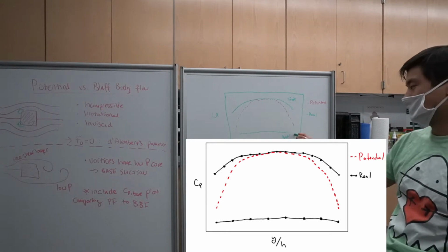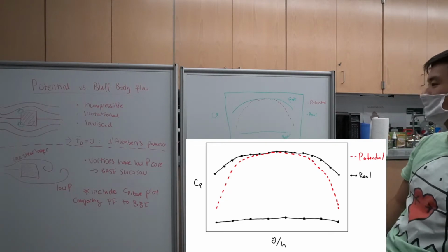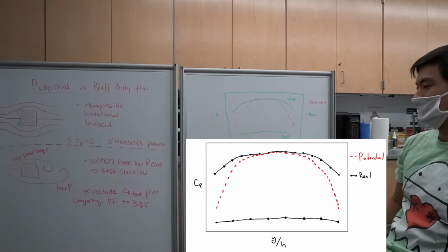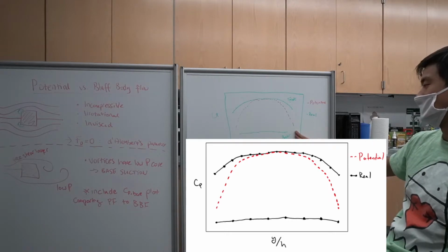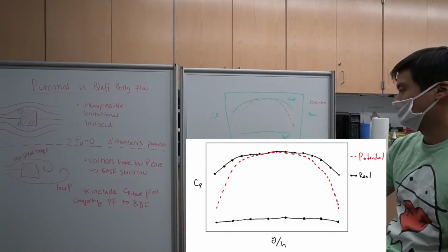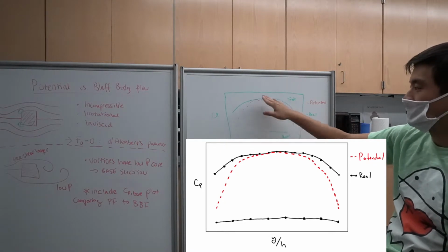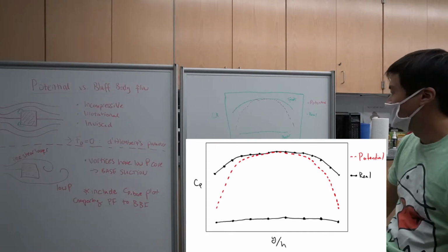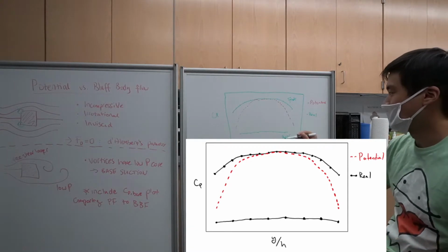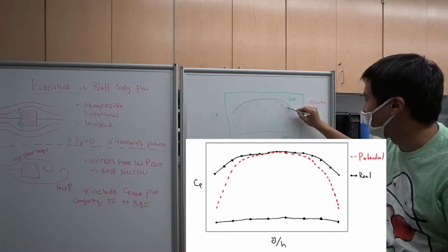Obviously the rear faces are very different, so with potential flow the rear face is exactly symmetric to the front face, and so we can see that there's only one line there, whereas as Sarah said, the rear face for the real cylinder, you get a very constant low pressure across the back face, which creates this suction. In contrast, for the front face, you get a high positive pressure. And so drag is actually the area between this front face and back face, essentially.